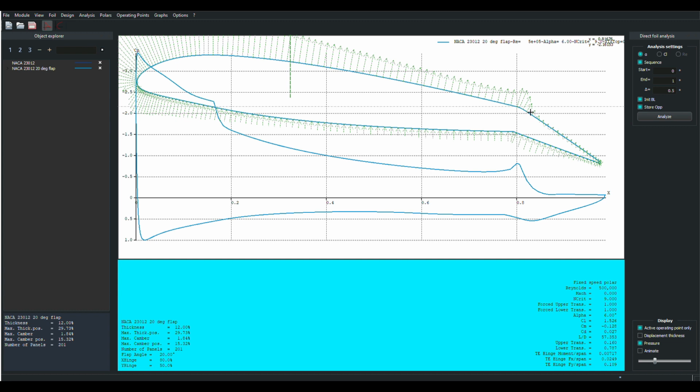But when we sealed that gap, it wasn't vastly improved. It wasn't like the problem magically went away. This is why: we probably weren't having very much flow through that gap, because the flow speed's very slow and the pressure differentials are relatively minor. What we had was a wall, and the flow couldn't get through the wall, couldn't go over the wall, so it just went out along the wing. 90-degree corner, an amazing thing to see.